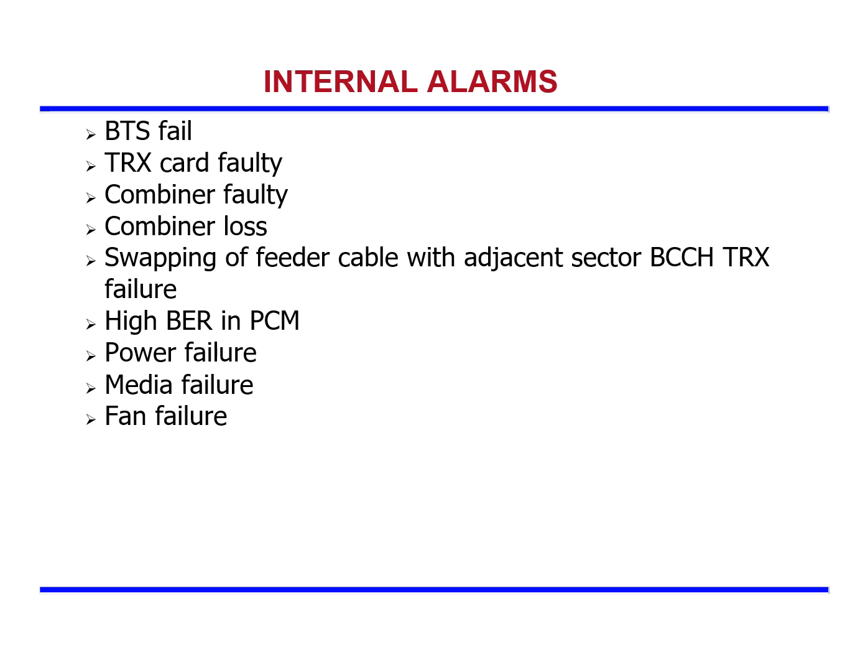Internal alarms are BTS fail, TRX card faulty, combiner faulty, combiner loss, swapping of the feeder cable with the adjacent sector, high bit error rate in PCM, power failure, media failure, fan failure.